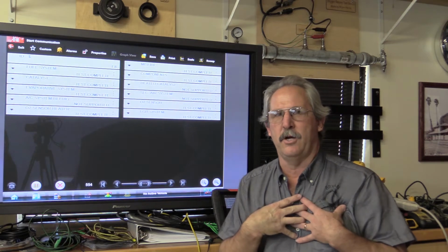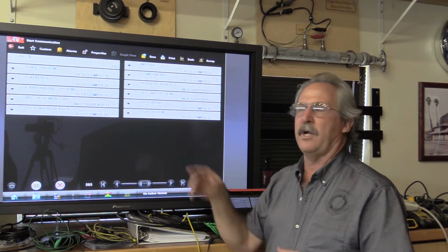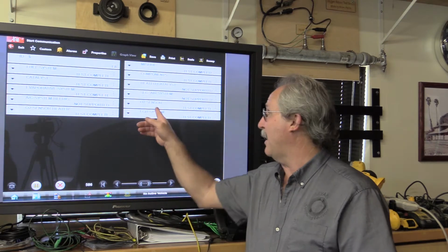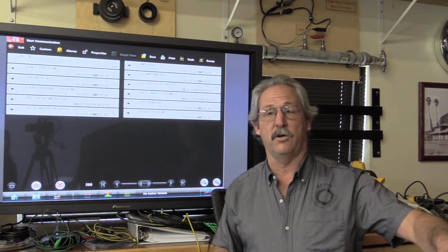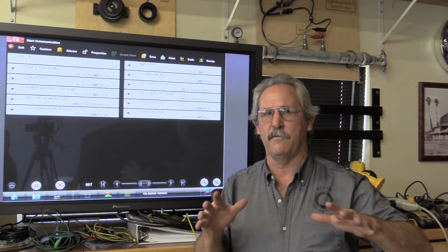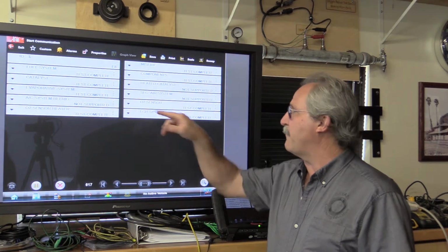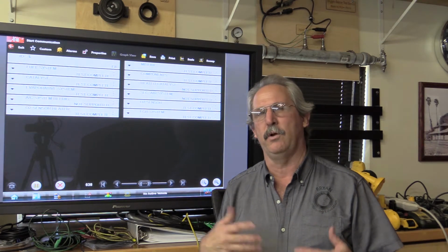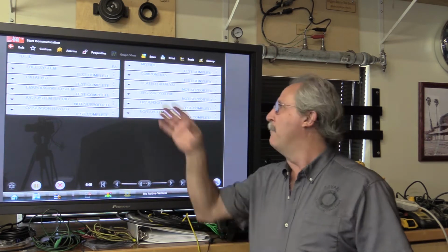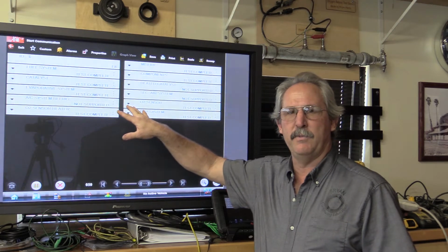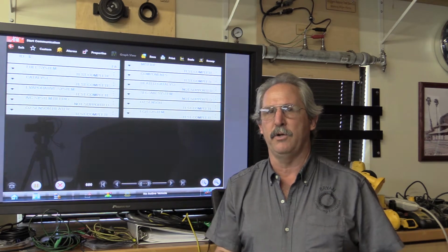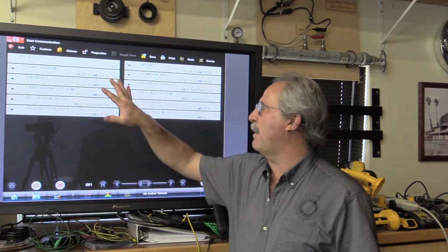I know from reading documentation, variable valve timing moved in with EGR, so if I have an EGR and variable valve timing, they both live here. In this case, this car does not have EGR. All it has is variable valve timing. So this is really my variable valve timing monitor, even though that's not what it says. So it's really important to understand more than just what the scan tool tells me and be confused. I need to understand how these systems are built and how they work. So this is my monitor status.